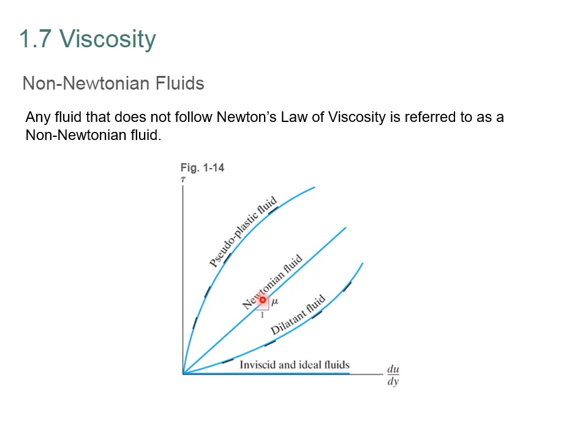For example, like a slinky. A slinky, you can stretch and it'll go back to its original form, but if you stretch it too far, it won't return to its original form. So here, even for this, for example, pseudoplastic fluid, if you limit the case to between here and there, it's sort of linear, but it's almost like piecewise linear, right? It's sort of straight over a certain section, but overall it kind of bends, where a true Newtonian fluid is strictly a straight line.